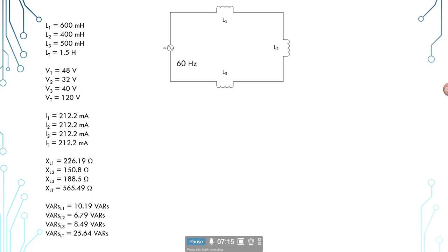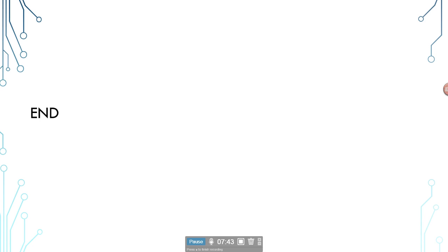Here's a list of all of our calculated values that we use as our baseline when we go out with our meters and measure this circuit with the live readings. We use them to compare so that we can contrast and see whether there's a problem in the circuit or not. If it's close, go look somewhere else. If it's out of the ballpark, foul ball over right field, then we need to look at that circuit a little closer because it has an issue with it.